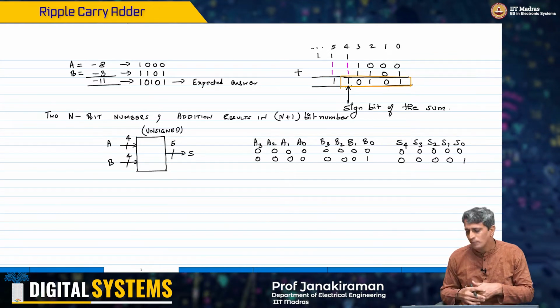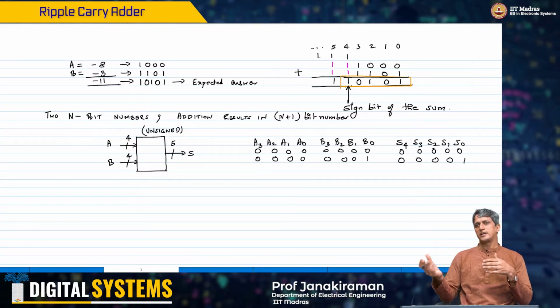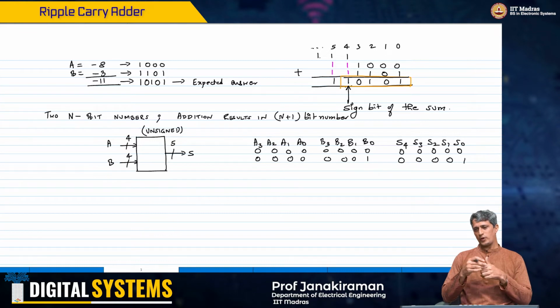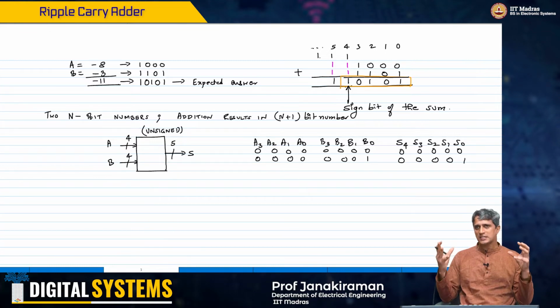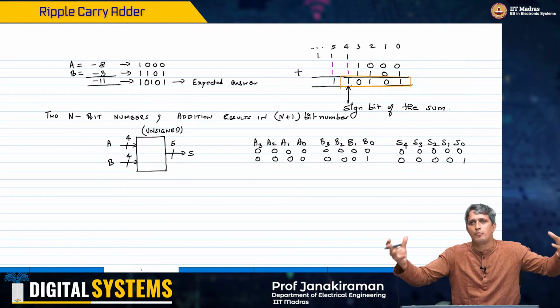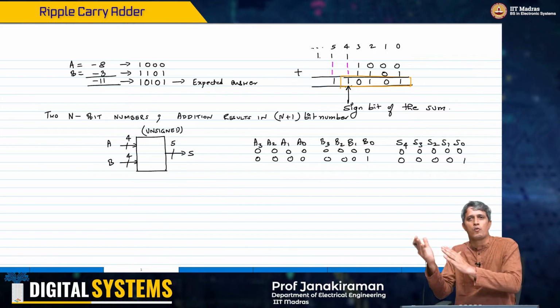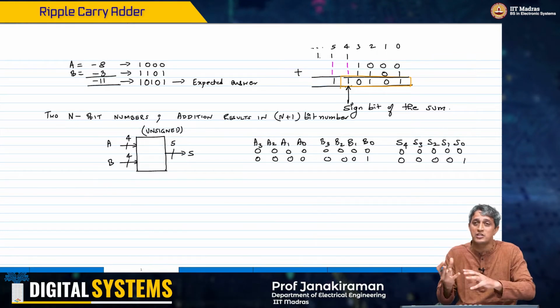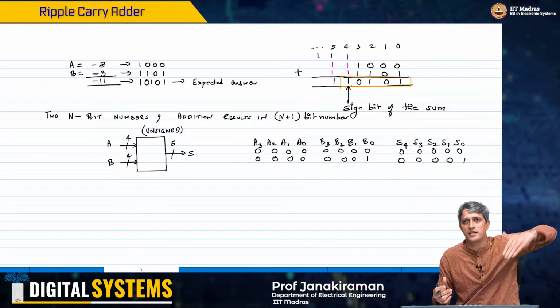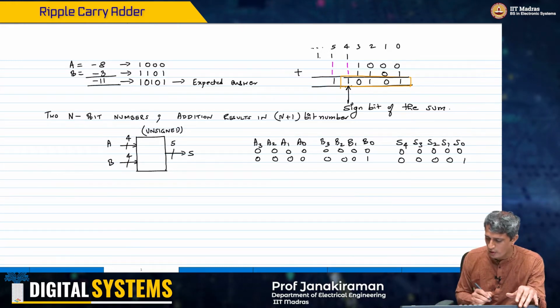Therefore in some circuits like the adder, and other circuits that we will discuss later this week, we can exploit a certain structure in the addition circuit, break this down into a 1-bit adder, and then use that to build the n-bit multi-bit adders hierarchically. So that is what we are going to do.